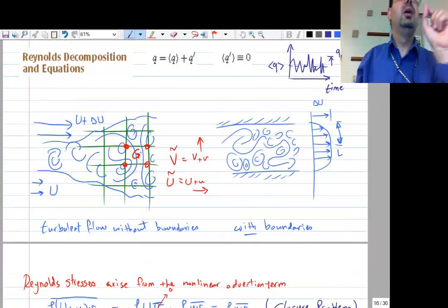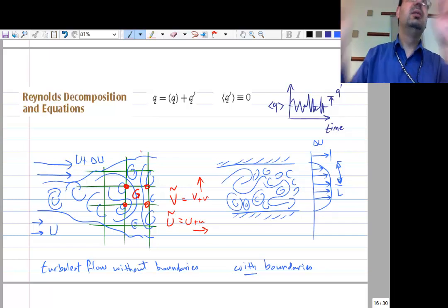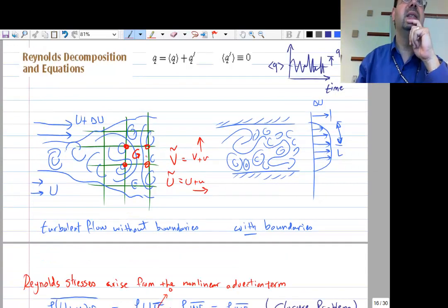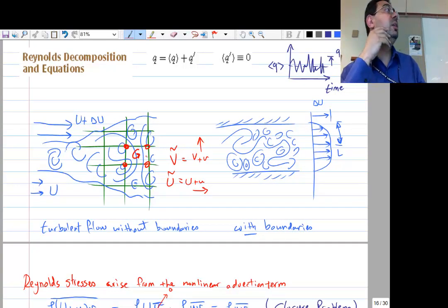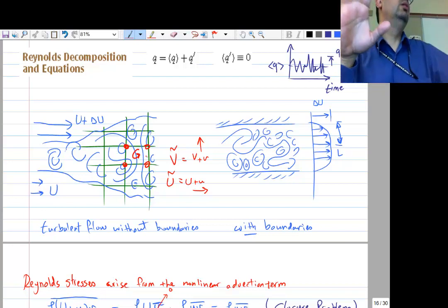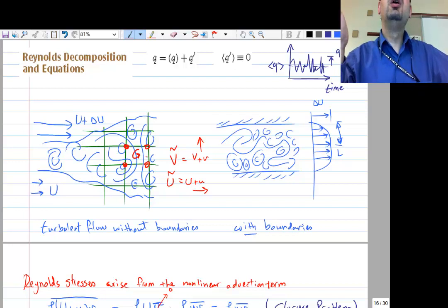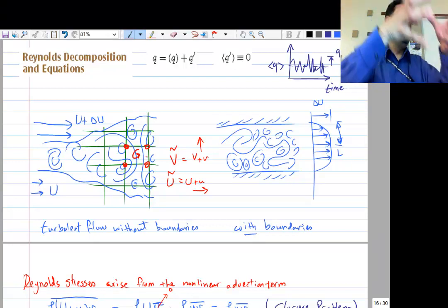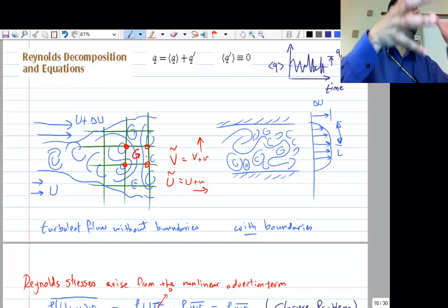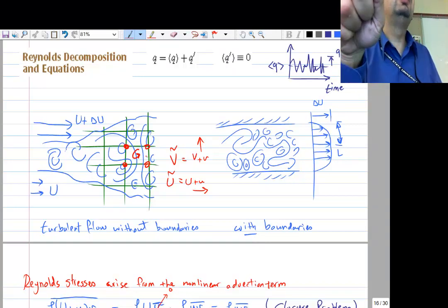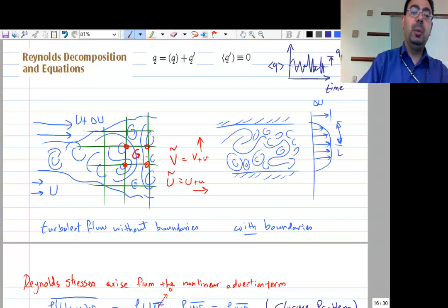So imagine if you are going to fit grid points in the smallest eddy of those guys, it turns out it's a disaster. It's a lot of data points. We're talking about billions of data points in the grid. However, they have supercomputers. We lost our biggest computer title to China now, but still we have the second largest computer in the world. So we can fit a tiny problem, not flow over an airplane, but a tiny problem, and solve it like this. When we do this, it's called direct numerical simulation.